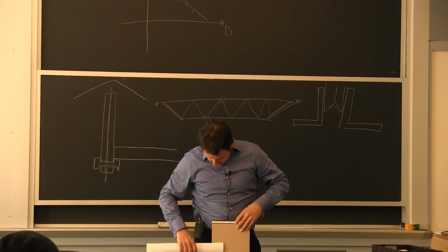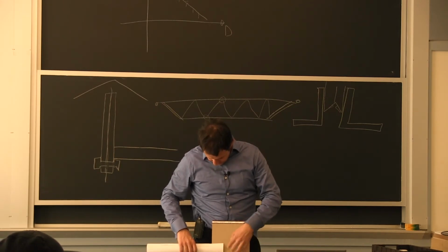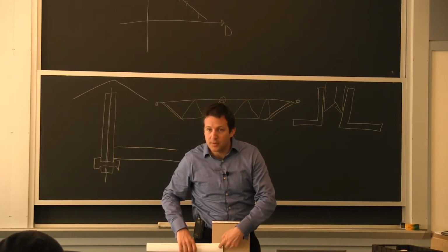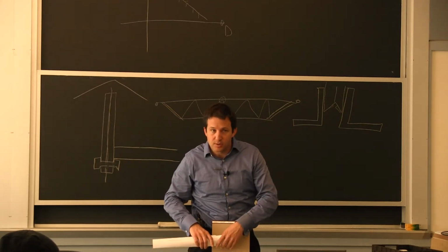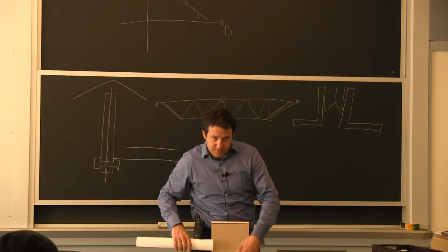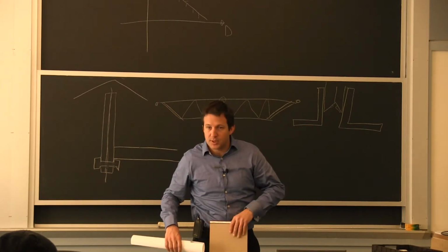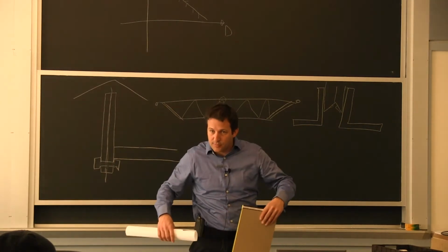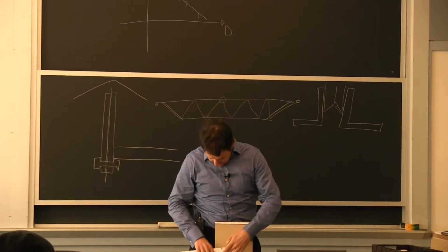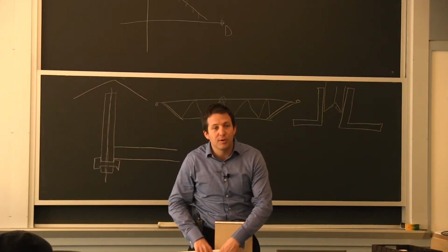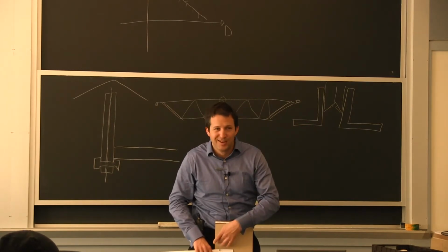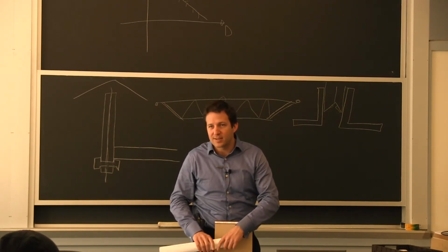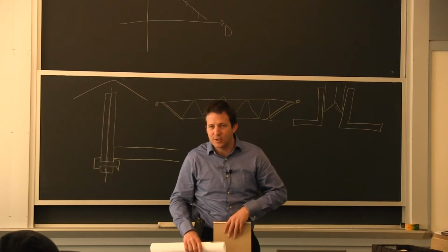It doesn't mean it has to be welding. You can put bolts here. If it's a flat member, you can have rivets. On the main bridge structure, you can have a pattern of 40 bolts or rivets, and that's how you make your connection. It's got a lot of redundancy, yet if you start having fatigue on the first bolt hole at the bottom and it starts cracking, it will continue. That's the problem with cracks: when they start, they typically don't end.